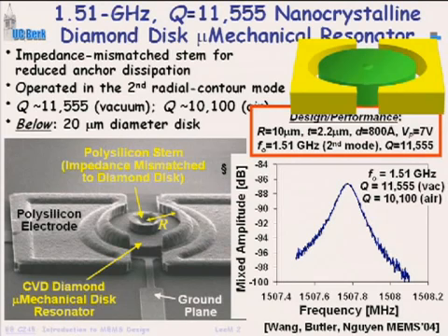Okay, it's even more interesting than this because it's even more like integrated circuits, electronic circuits, in that when you go to higher frequencies in a circuit, what becomes more important? Does resistance become important, or does capacitance become important, and inductance, right? When you go to higher frequencies, suddenly those resistors are no longer there, and it's all capacitors and inductors.